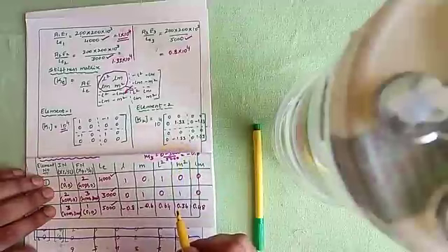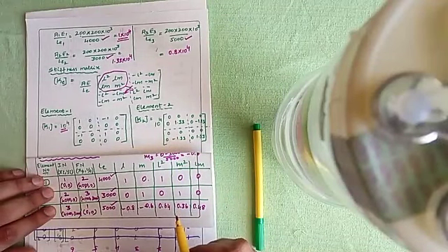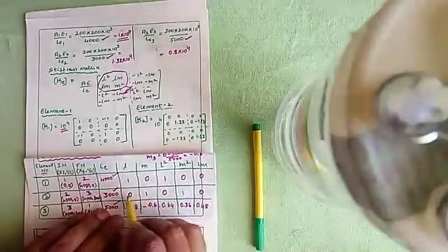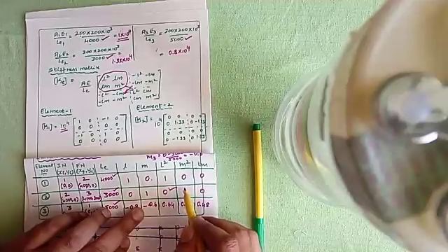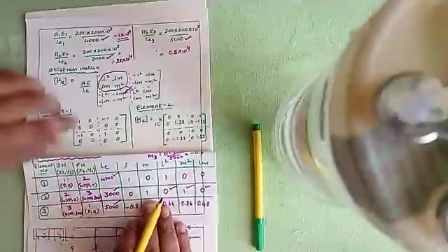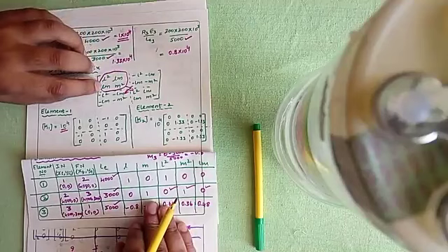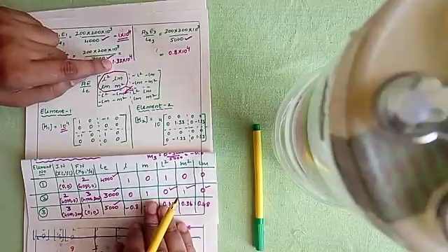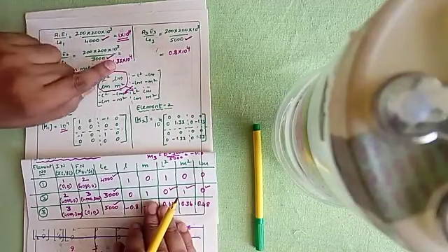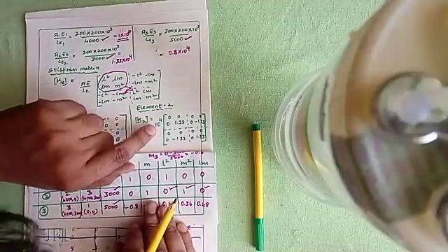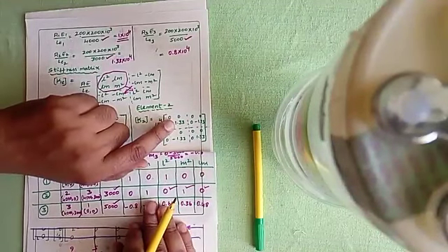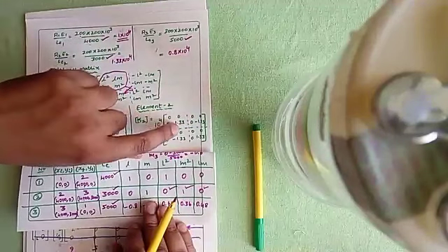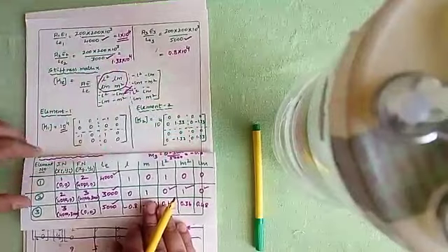Now let us come to element number 2. From your element table data, you can see that L² is 0, M² is 1, and LM is 0. So L² is 0, LM is also 0, and M² is 1. When you multiply A2E2/L2, you are going to get 1.33 × 10⁴. So I have kept 10⁴ common, and I have multiplied 1.33 with the stiffness values inside the bracket. So you're going to get plus 1.33, minus 1.33, 0, minus 1.33, and plus 1.33.